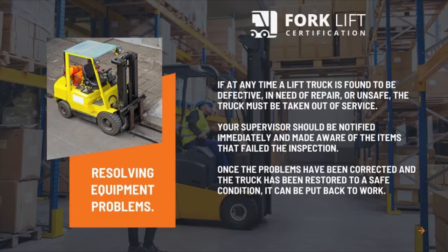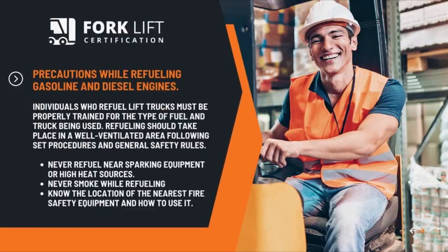Precautions while refueling gasoline and diesel engines. Individuals who refuel lift trucks must be properly trained for the type of fuel and truck being used. Refueling should take place in a well-ventilated area following set procedures and general safety rules. Never refuel near sparking equipment or high heat sources. Never smoke while refueling. Know the location of the nearest fire safety equipment and how to use it.